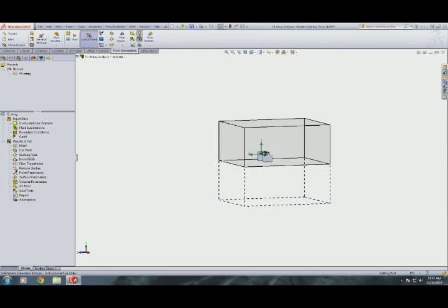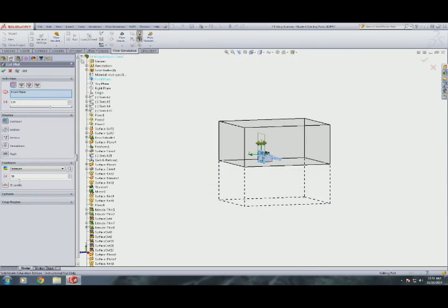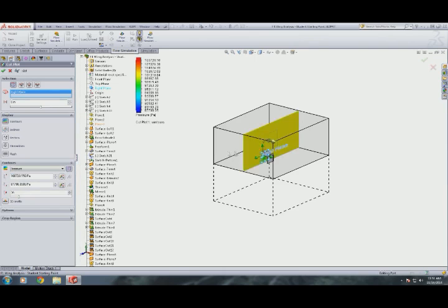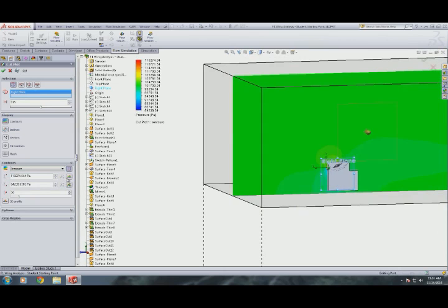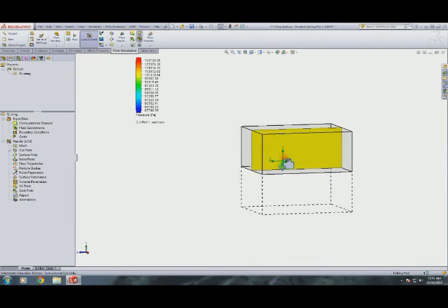These are the plots you have to make to turn in. Let's make it on the right plane. So expand the tree, click right plane, yay. Contours, pressure. Now this is the number of color gradients. 10 is the default, which makes it look really terrible. So 36 would be good. Set it to plot min and plot max with those two buttons there. Get a preview of what's going on, and alright, that looks fine. Actually, I hate that kind of puke yellow color. But whatever. Let's say okay.